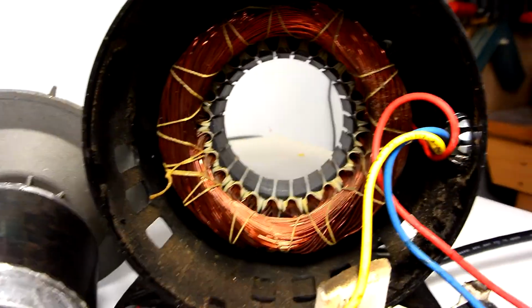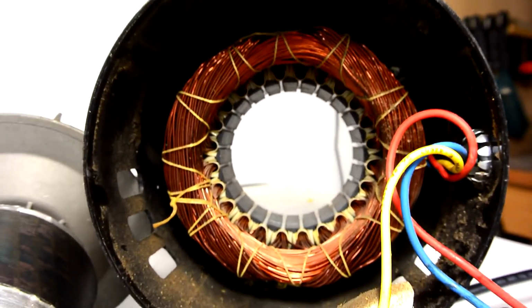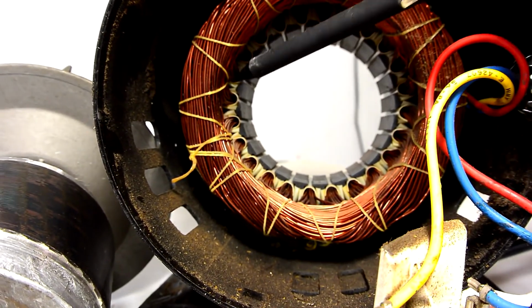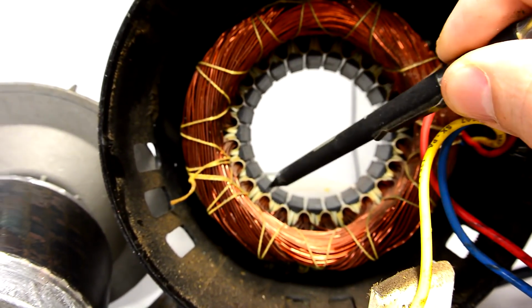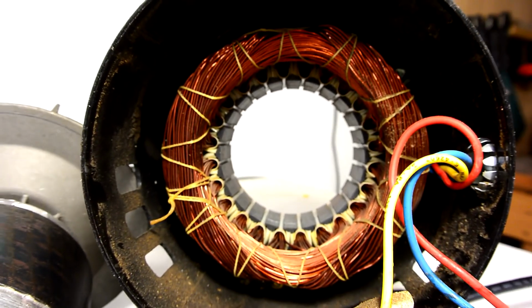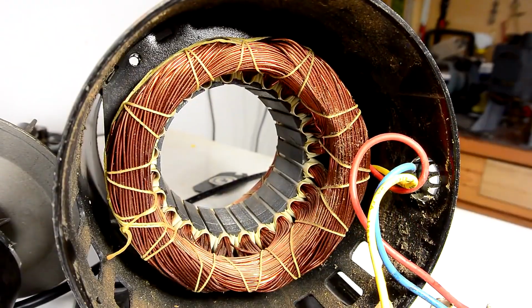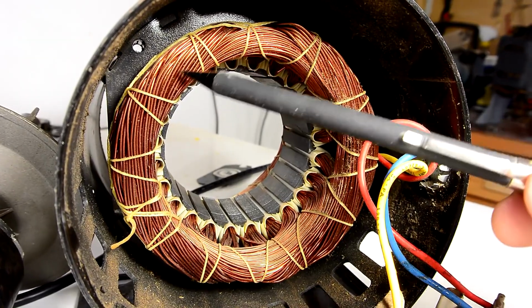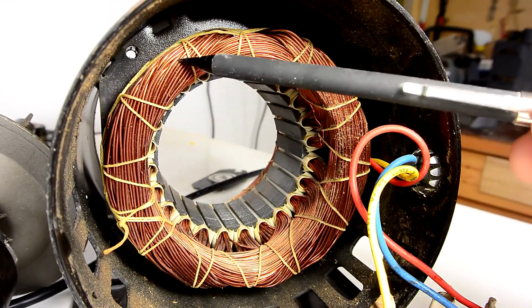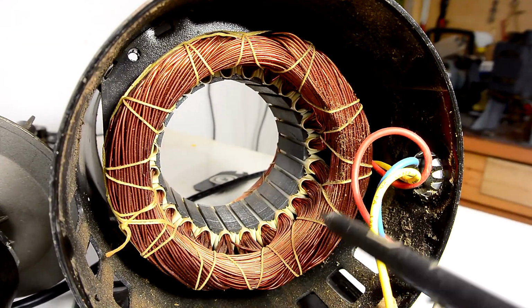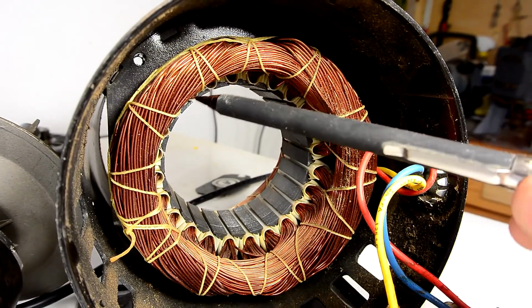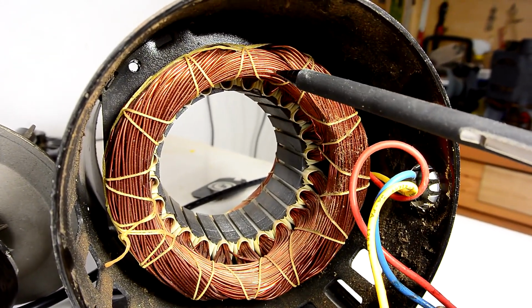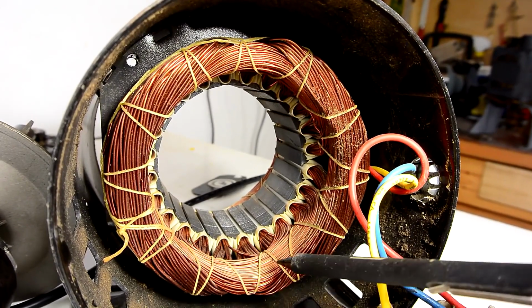Now if we look inside this 3/4 horsepower motor, you can see the windings are not as easy to discern. Essentially the winding is split over many slots in the stator here, and that makes the transition from pole to pole a lot smoother, which makes for a quieter, more efficient motor. Looking closely at the windings, you can see there's a winding that goes here, and then there's another one that goes here, and that's made out of thicker wire, and that's the main winding. And then we have another winding that's kind of to the inside of that, that's made out of thinner wire that goes here and here.